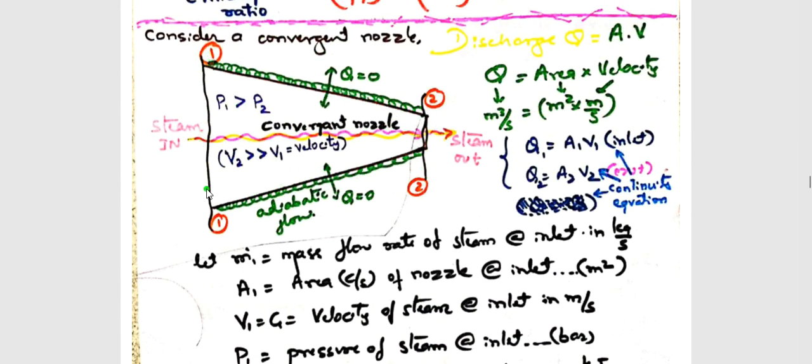Initially enthalpy is more, high pressure, high enthalpy steam when passed through the nozzle, expansion takes place here, due to expansion the enthalpy of the steam decreases. So that decrease or drop of enthalpy, where has it gone? There is no chance of going outside because all surface boundaries are insulated. So that decrease of enthalpy of the steam has increased kinetic energy.